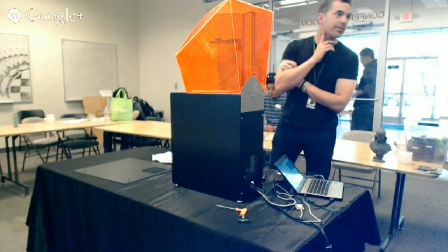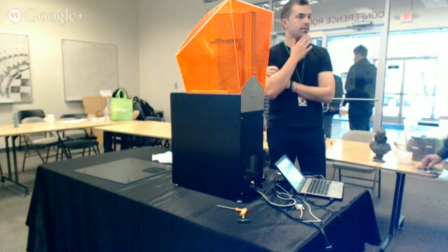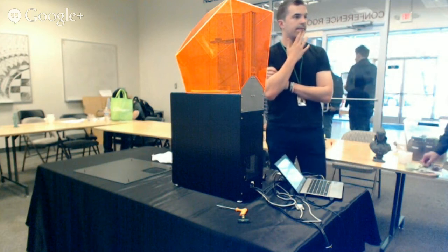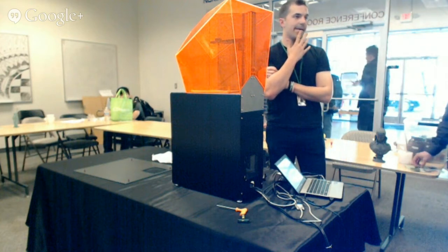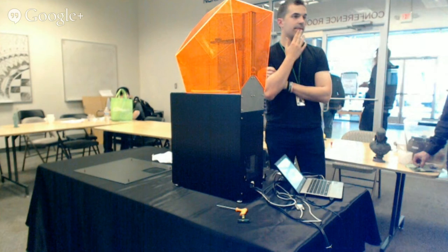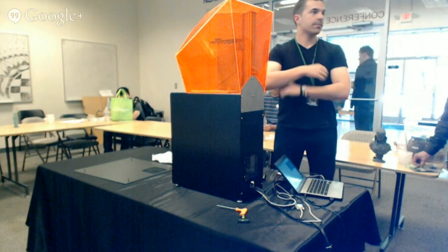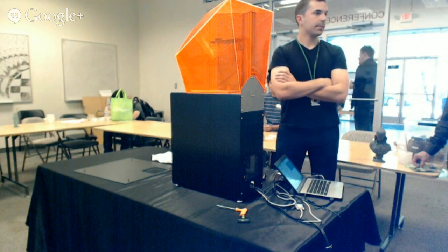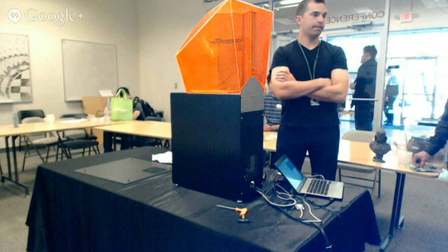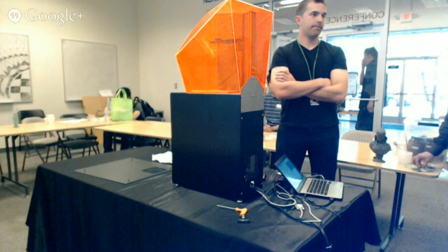because those printers are climate controlled, and so everything about the slicing algorithm is closely tied to the material properties that they can control for. With a maker printing open things, there's a limit to how good you can print, because you don't have control over the climate, and you don't have a match between the printing temperature and the material. We have many different materials you buy from different places. They have different material properties. Their curves of how soft they are at different temperatures vary. And of course, I don't have temperature control.